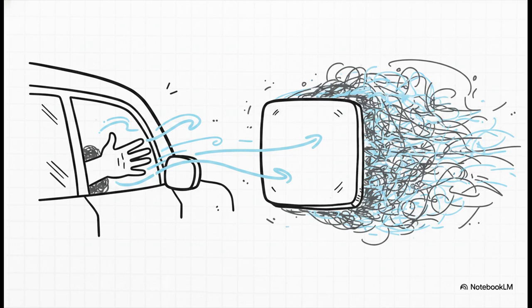Parasite drag is super interesting because it's not associated with creating lift at all. It strictly comes from the physical displacement of air by the aircraft and the turbulence that gets whipped up in the airstream. Just think of sticking your hand out the window of a moving car on the highway. Now, form drag is actually a specific piece of parasite drag, but it's generated purely by the overall physical shape or design of the aircraft itself.